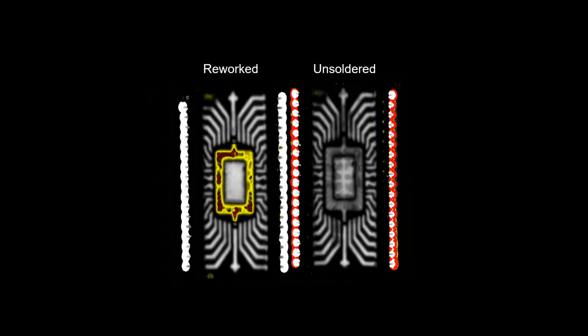This part was brought to us for failure analysis because it was failing prematurely. The root cause of the failures was determined to be that the parts were delaminating. Even when they passed the test, they had a latent defect that could cause premature failure. It was determined that the delaminations were caused by prolonged high heat of a soldering iron.